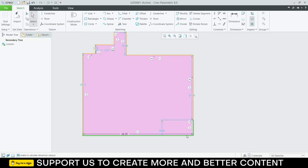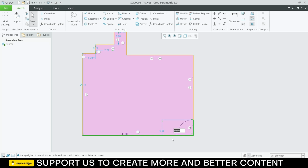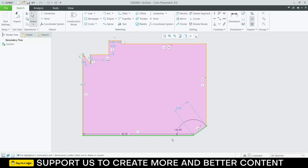By pressing Ctrl, select these two lines. Click on angle. Now notice that there is some constraints. So because of the constraint, I can't change the dimension. So click on this one and delete this. Now give it angle. In my case, it is 144 degree, and its length will be 42.